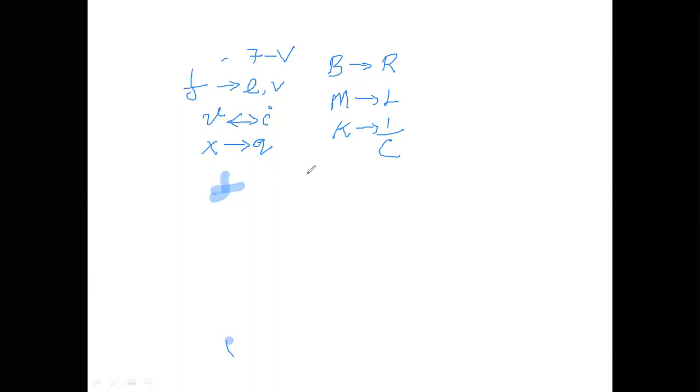In the case of force current analogy, you just see the variable force F should be replaced with the current I. You just see the differences. Here it is E or V, here it is I. Understood? For the velocity element, it should be the voltage element. For displacement X, in this force current analogy, it is flux phi.